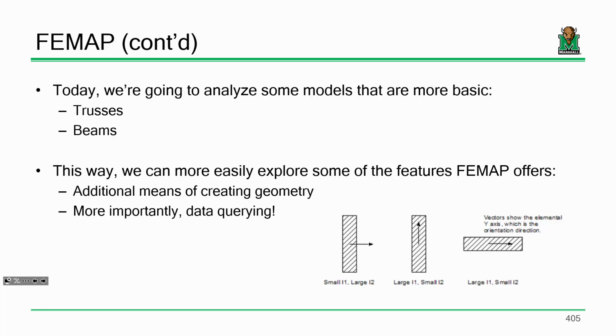When we did that 3-dimensional beam last time, if you took any one element, there's stresses in the x direction, stresses in the y direction, stresses in the z direction, displacements all different which ways, shear stresses, reactions. I mean, there's a lot of data that corresponded to just that one little problem. What we're going to do here is look at something like a truss because the output's pretty simple. When you look at a truss, you only get one output from each element, and that's the force inside the truss member. That's it. So we're going to do this to scale down our problem a little bit.